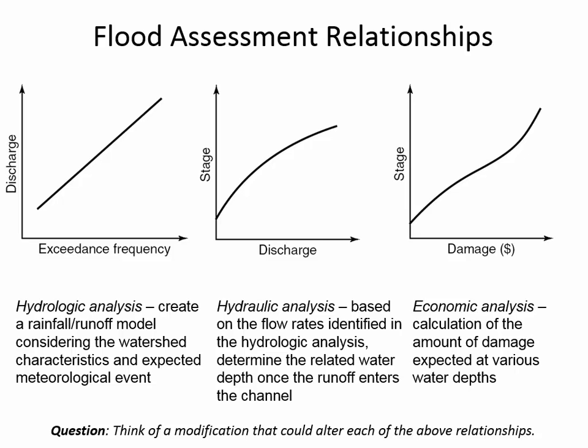So maybe in your notes you should say the good thing is for this curve to be low. This first curve, low is good because remember, runoff is a problem in the eyes of an engineer. Maybe in the eyes of a farmer, runoff is a good thing because they can use it to irrigate their crops, but we're looking at water as a problem that's causing flooding and ripping up the stream. And so urbanization is going to make that curve higher, and the engineer is going to look for some way to make that curve lower. So it could be the ponds, enhancing infiltration, restricting urbanization, and so on. Okay, so what about this next one?